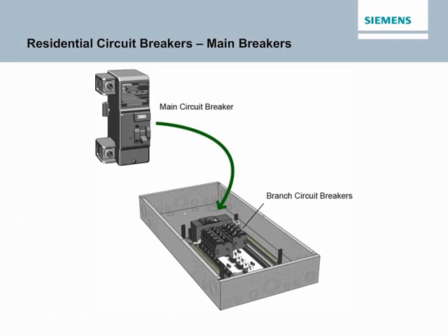The main breakers or main breaker kits for PL load centers have continuous current ratings from 100 to 225 amps. The interrupting rating for these main breakers is 22 kA. Single-phase factory installed 22 kA interrupting rating main circuit breakers offer a 22/10 kA series combination interrupting rating when used with 10 kA type QP, QT, QPF, QE, QN, and QAF branch breakers.